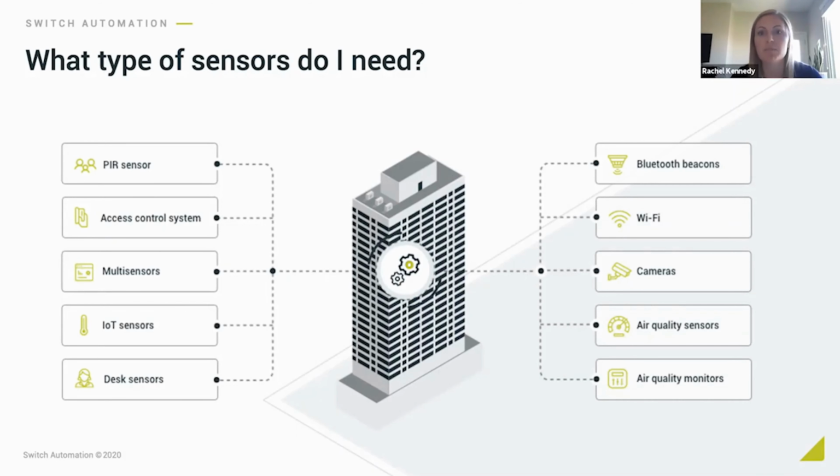When we think about some of those different multi-sensors, again, a lot of the pros are that they have multiple different data points within one sensor, but they often require a retrofit, or you're going to want to be installing them separately. So it does allow that flexibility of not necessarily needing some infrastructure underneath, because they can communicate wirelessly or by running power and data directly to that sensor. But that does provide the bonus of the high granularity. You're not requiring active users, or in the cases of Bluetooth beacons and Wi-Fi, that people have those turned on. We're going to capture those measurements of the people for occupancy in both cases.